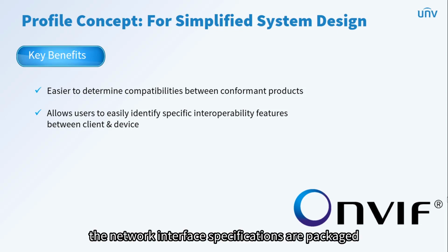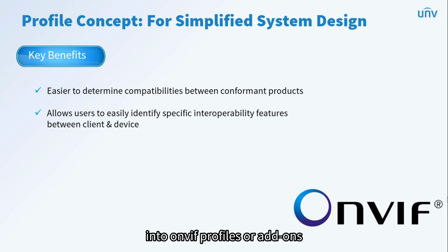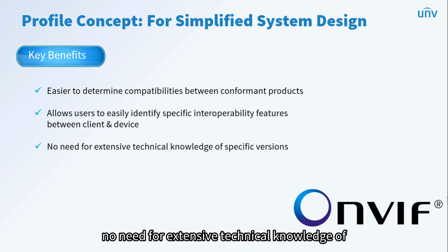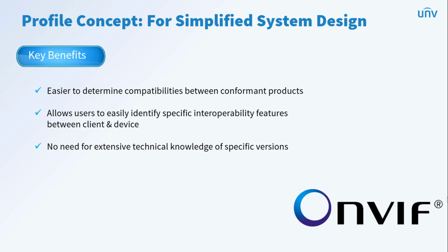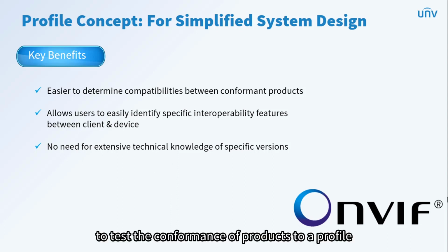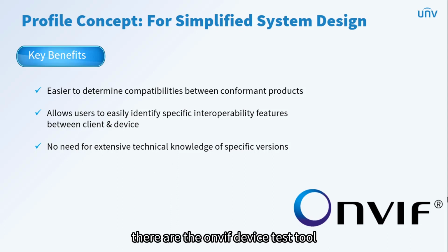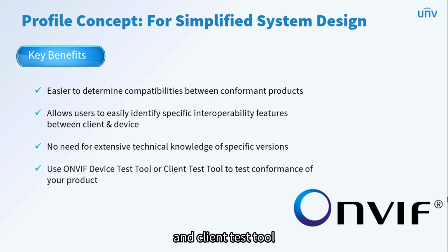The network interface specifications are packaged into ONVIF profiles or add-ons. So there is no need for extensive technical knowledge of specific versions. To test the conformance of products to a profile, there are the ONVIF device test tool and client test tool. ONVIF profiles make interoperability between products of different brands easier and more effective.